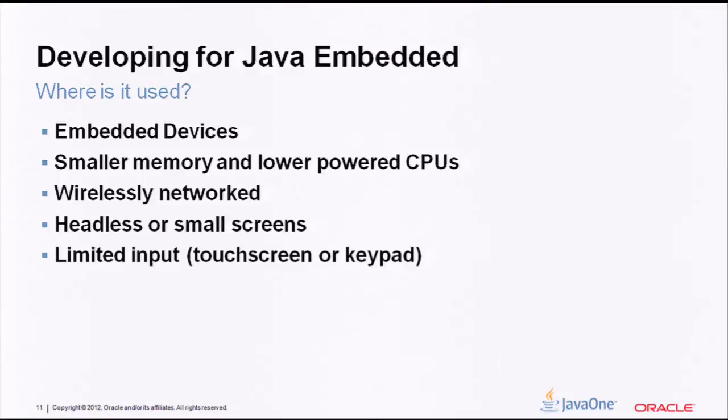And then also on the UI side, you have to make sure to account for things like headless use on a network router. There's no screen, no set of buttons that you're pressing. So you have to make sure you're programming your application to handle that and be able to be configurable even if it's headless. Or it might have just a small screen, small LED screen. And then you want to make sure to address the input device, such as a limited keypad or a touch screen. How is the user going to enter in data, and how much data will they be able to do on this limited device?